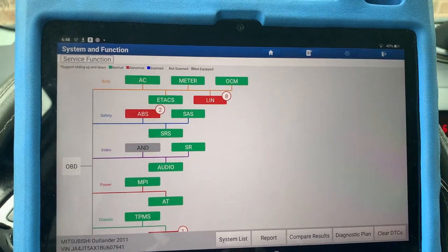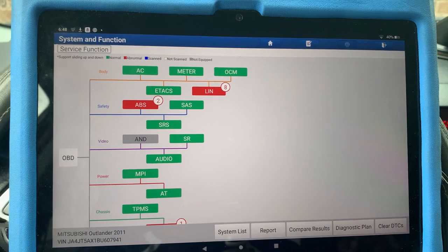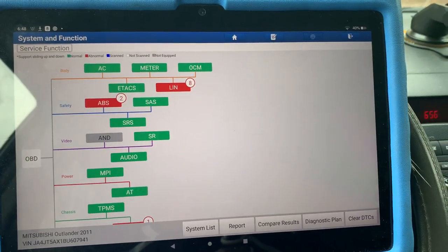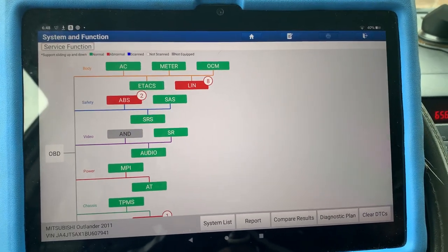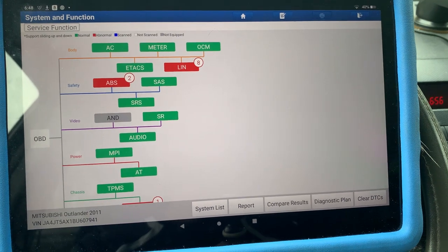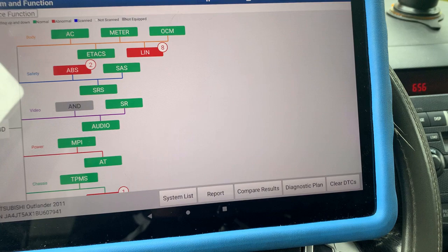I put the multimeter at the blower connector down there, and I got 12 volts. I'm not going to do that again, but that's not a final decision, because having voltage over there doesn't mean the circuit can carry current.